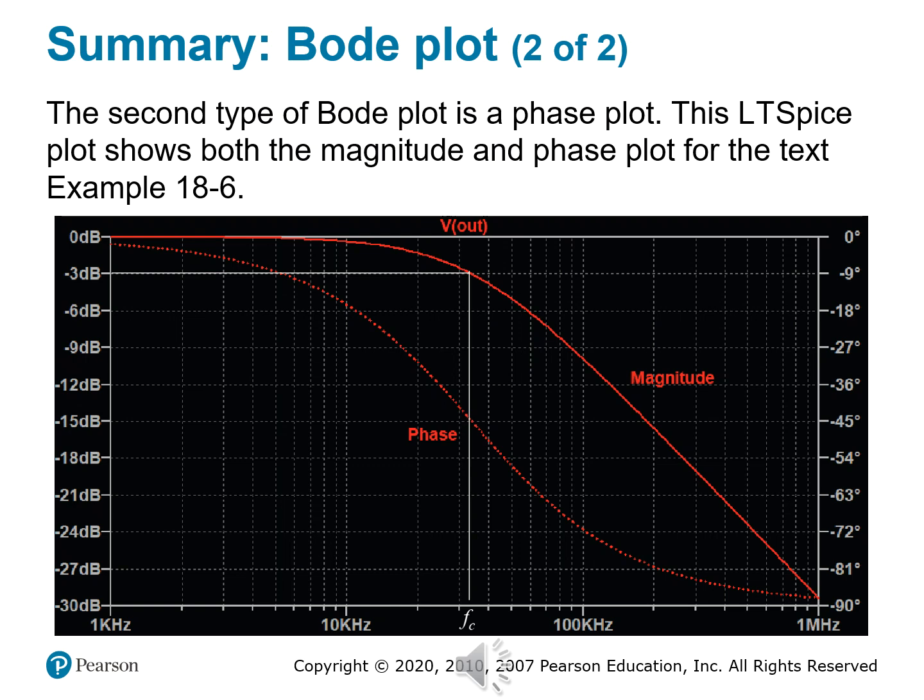You're going to see a dual-axis graph, and it shows both the magnitude response, in this case, you see that in the solid red line, and you're going to see a phase response, which is denoted in the dashed red line. So as frequency increases, the magnitude line shows us how the amplitude of that signal drops, just as we expected from a low pass filter.